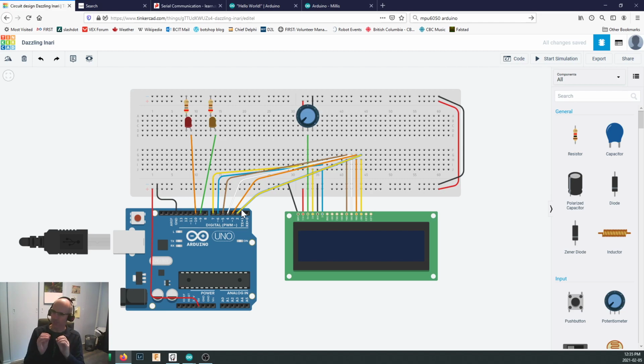And whether the line was twisted and kinked was making a difference in the data. So you couldn't pulse a parallel port as fast as you could pulse a serial port. Because if you pulsed it really fast, then you would get a discrepancy between when the data on this pin arrived and when the data on this pin arrived.